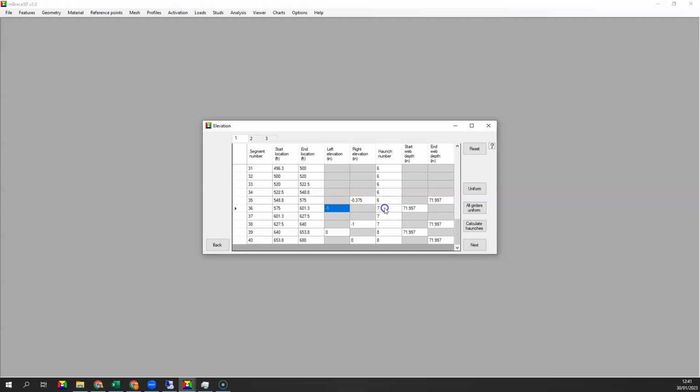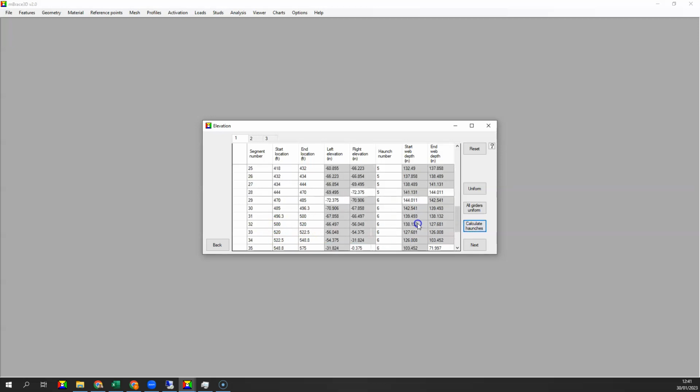8. This is just a convention, of course. This portion of the bridge is flat with a constant web depth of 72 inches. These are the few parameters that you need to enter. You can see here we've got 40 segments, and all you have to do next is to click on this button, which will automatically calculate the equation, the elevation at the start and length of each segment together with the web depth. So we believe this is a really useful way.